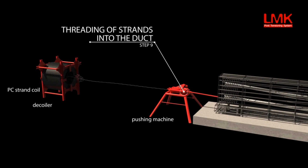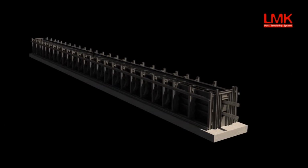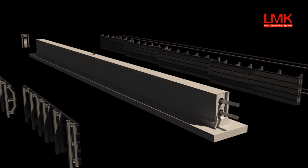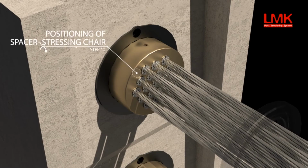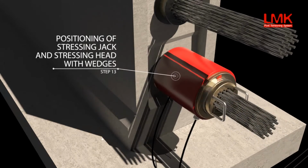Prestressing means the artificial creation of stresses in a structure before loading, so that the stresses which then exist under load are more favorable than would otherwise be the case. Since concrete is strong in compression, the material in a beam will be used the most efficiently if it can be maintained in a state of compression throughout. Provision of a longitudinal compressive force acting on a concrete beam may therefore overcome both of the disadvantages of reinforced concrete. Not only is the concrete fully utilized, but also the need for conventional tension reinforcement is removed.